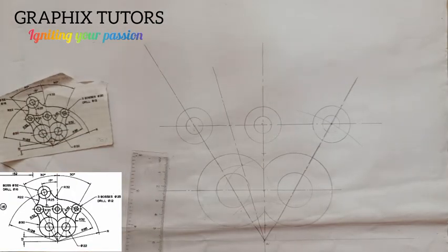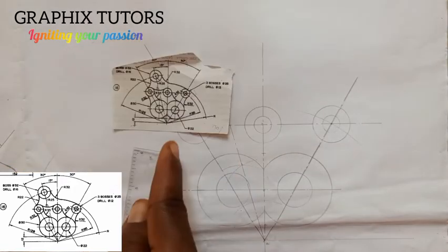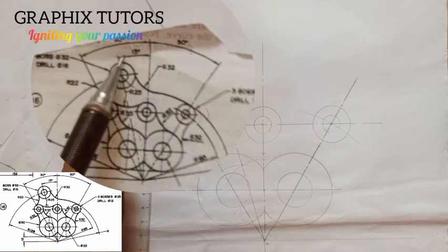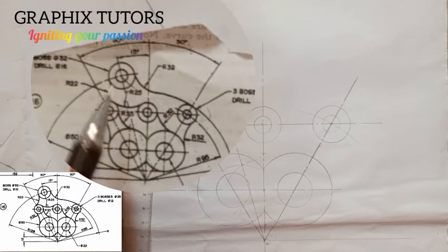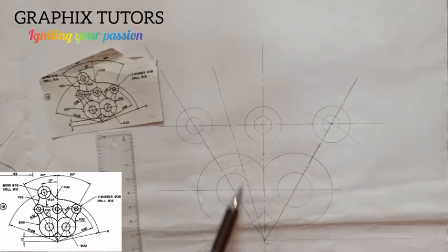Now, there's another bigger circle up here. And for me to get the center, the circle is lying on the 15-degree line. If you look at this center line here, this one here is inclined at what? 15 degrees to the what? Vertical. And the center is gotten from the radius of what? 126 on that 15 degrees. And this is my 15-degree line here. But I need the radius of 126 to get what?